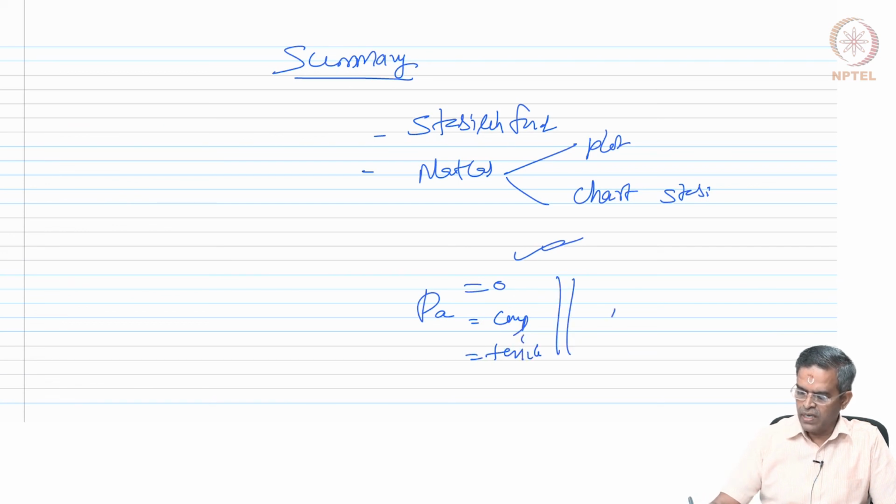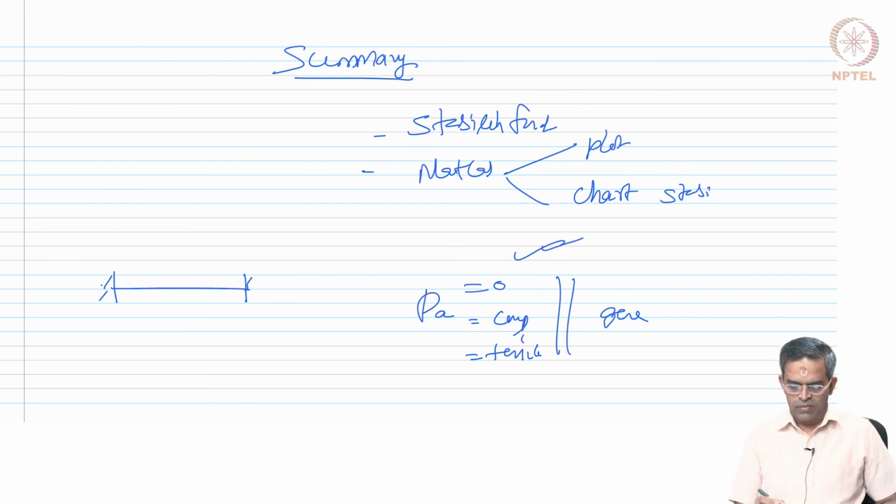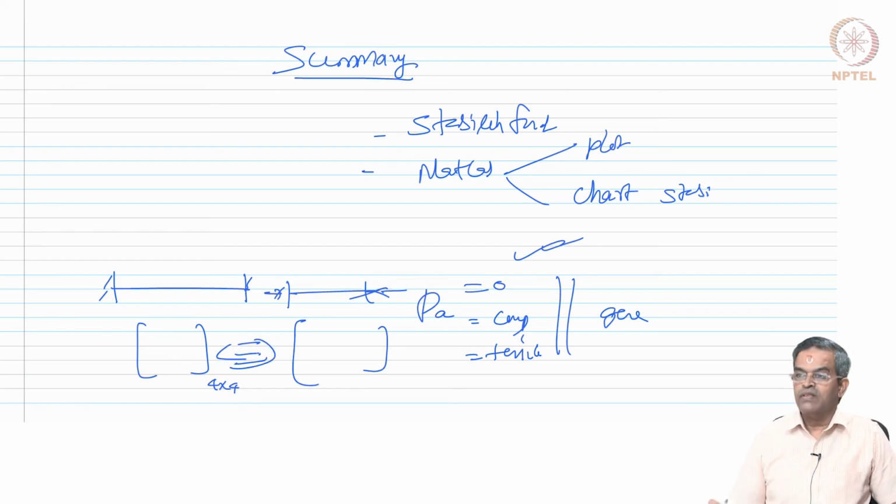We have developed a generic case, and very interestingly this compares very well with the standard fixed beam derivation without axial load, with the same algorithm. This is also 4 by 4 and the stability function is also 4 by 4, so there is an absolute similarity between the two derivations. That is the beauty of the whole exercise. You can easily remember this and teach it in class in the same order. So the stability derivation becomes very simple, like a stiffness analysis of a fixed beam.